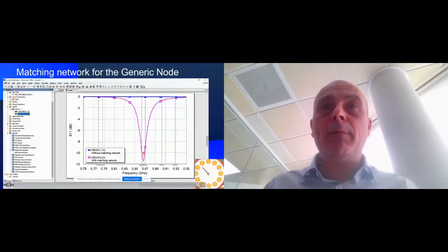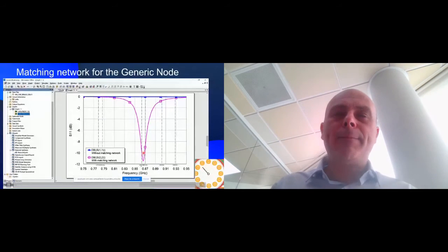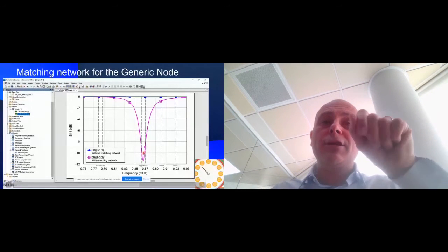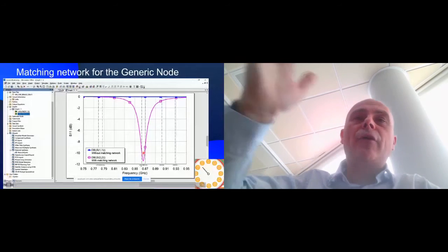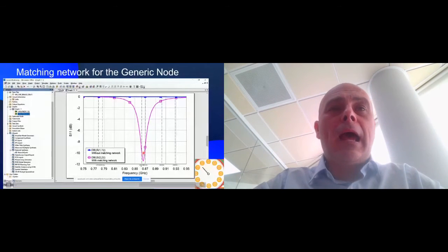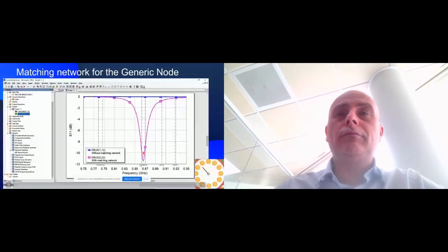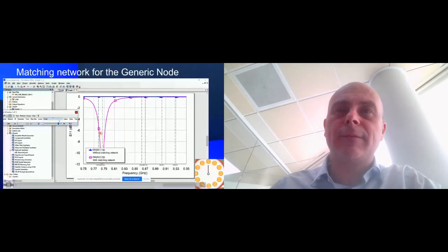And we can repeat this experiment for including all other LoRa frequencies. Let's do perhaps another thing easier. Let's take this component and let's tune it. Let's change the value of this inductance, increasing and decreasing the value. And what you can see is by increasing this value, you can change the response, and perhaps now you can operate in the LoRa in some Chinese frequencies.